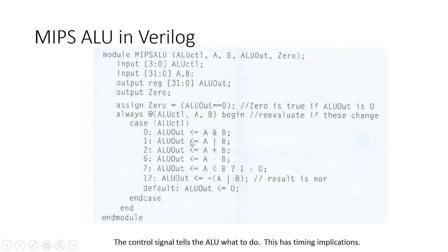into one of these cases. So it's not like what you might be used to in C or Java or Python. I'm trying not to date this lecture, but whatever the current programming language of choice is, don't read this like a standard case statement that goes through each one of these and checks them. No, it creates a separate simultaneous operation for every one of these, and so whatever case it is, if one of these has occurred, it automatically goes to that case and then performs whatever logic needs to be accomplished immediately based on the new value.